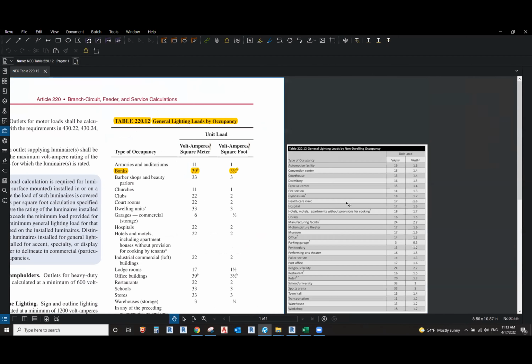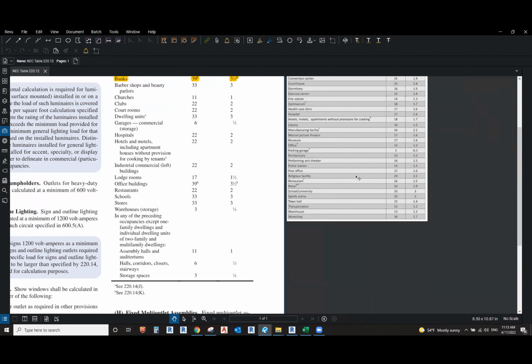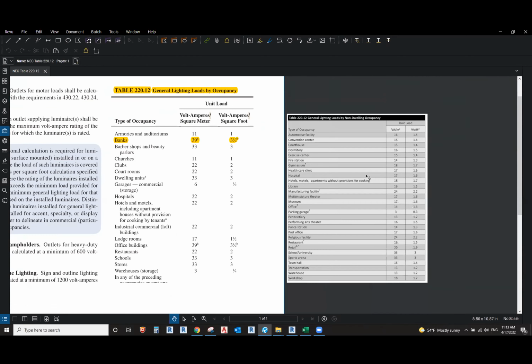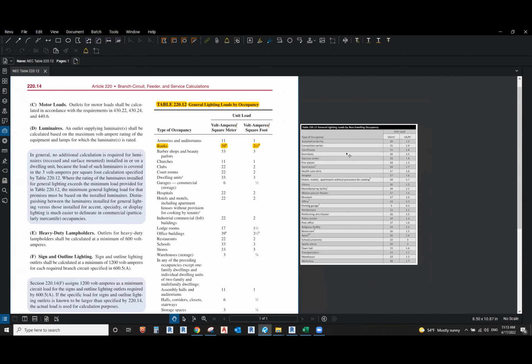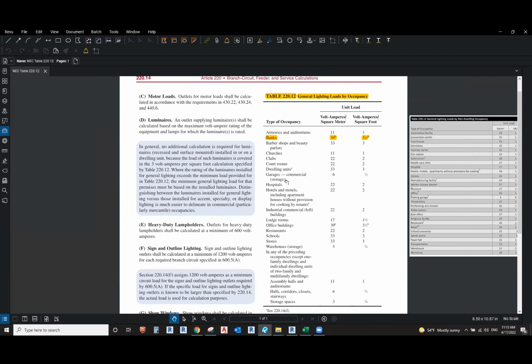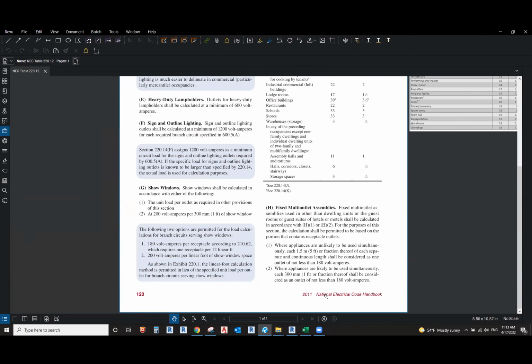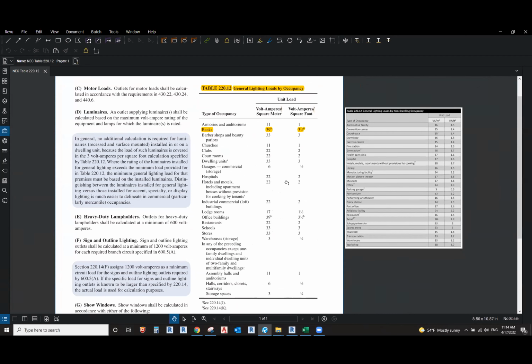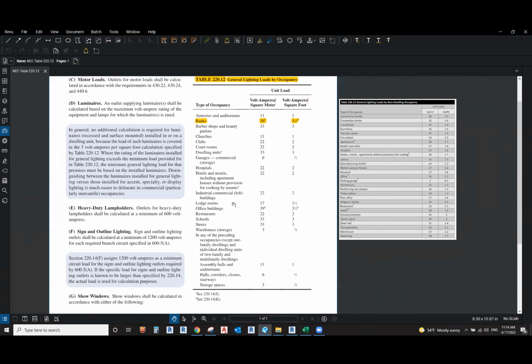that's not referenced by the NEC code. Oh, okay. Yeah, that's something I just copied from somewhere else. But it should be IEC or some other reference like a European standard. There are a lot of standards, Asia has its own standard, but if you are in the US, we have to follow the NEC code. That's what they call the National Electrical Code. Okay. So we can use this number, but your design will not be that accurate. If you want an accurate design, then reference the NEC code. That's what we are using in our design.